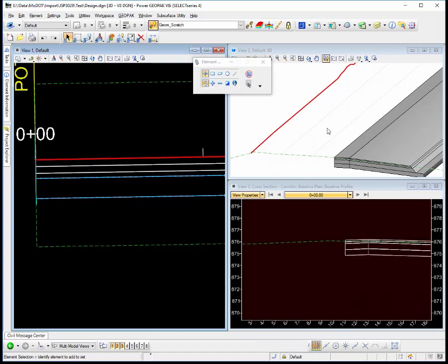And so I really don't even need those point controls now because I'm parallel to my baseline. If I weren't parallel to my baseline, perhaps you might need to use one of those point controls and alignment for simply a horizontal control and not a vertical control. The key here is to not use the vertical profile of the existing ground if you don't have to.